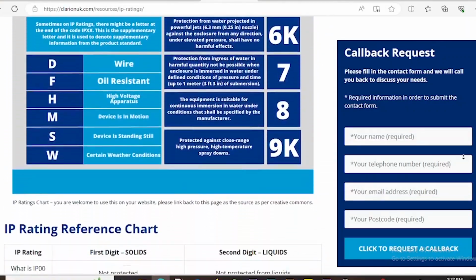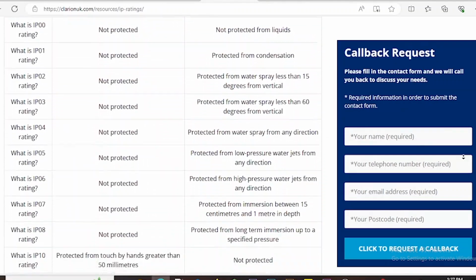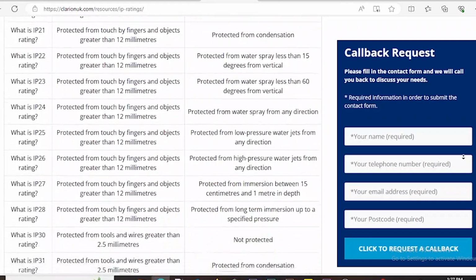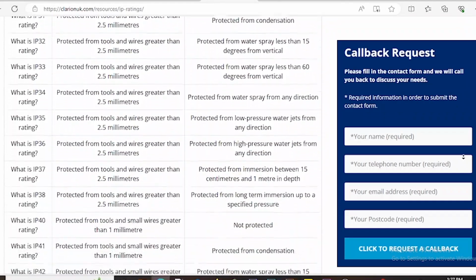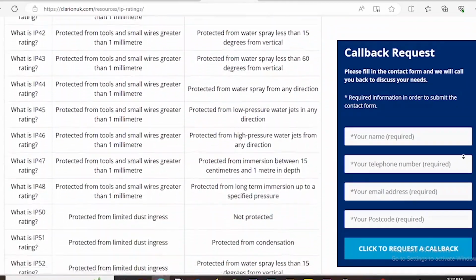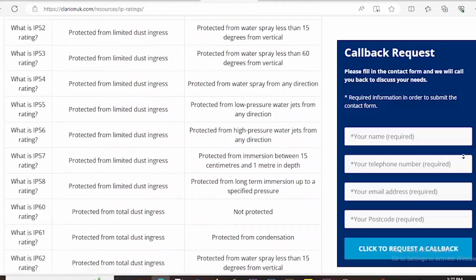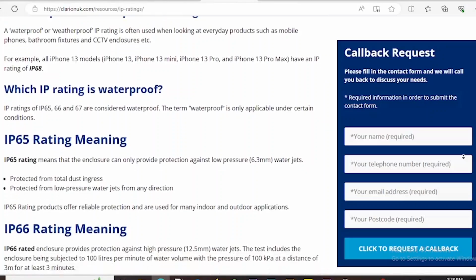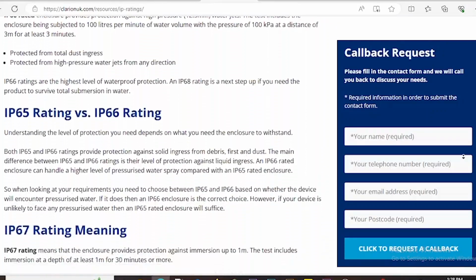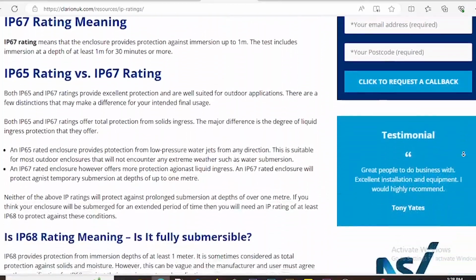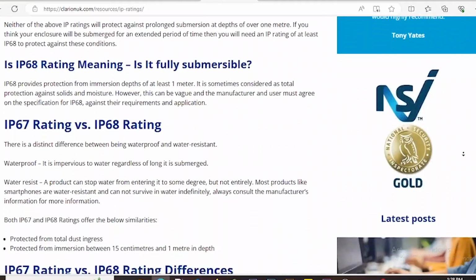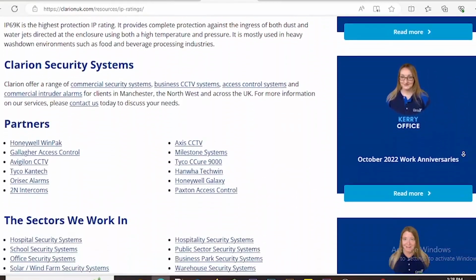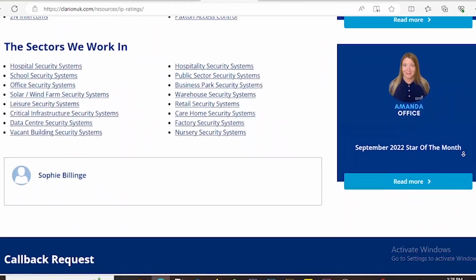What are these improvements? If you plan to keep this as two pieces, which means you don't have a separate compartment for the battery storage, so the battery is with the light. The light section can generate some thermal heat. So you couldn't increase the battery capacity as it is, because if you increase the batteries, they need some breathing space. Then the batteries could heat up a little, and with all the components in a single box, any battery short destroys the whole product. So that is the next stage of improving this product.